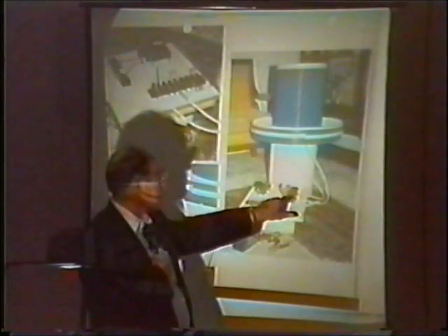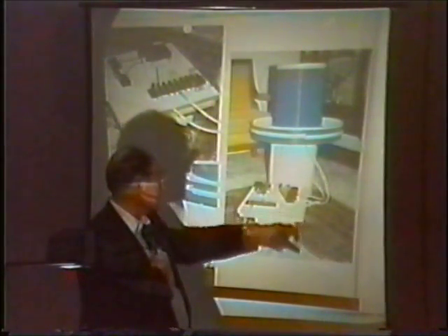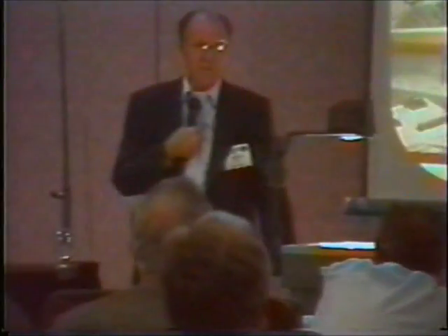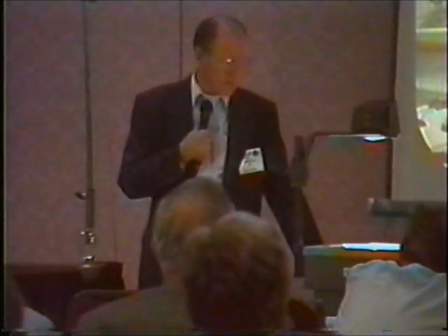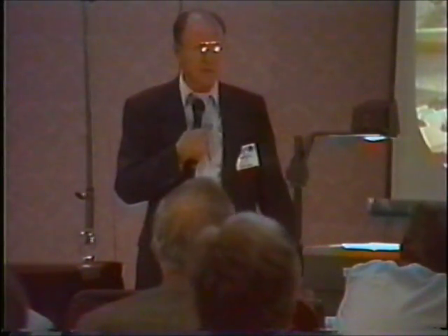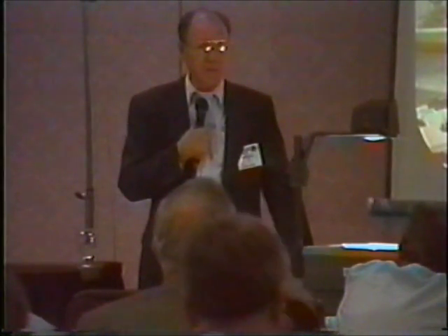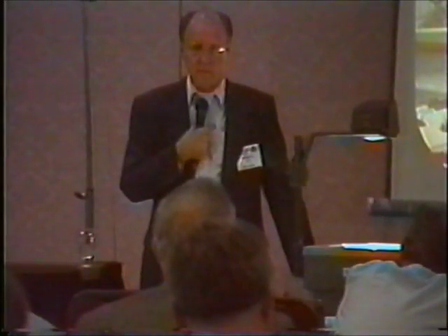So between those two, in relation to your other things, you've got this 10,000 volt reconstituted mica capacitor. They take mica and break it up in little bitty pieces, and they mix it into a glass ribbon type deal, and that becomes your dielectric in this particular case, and they go to very high voltages.